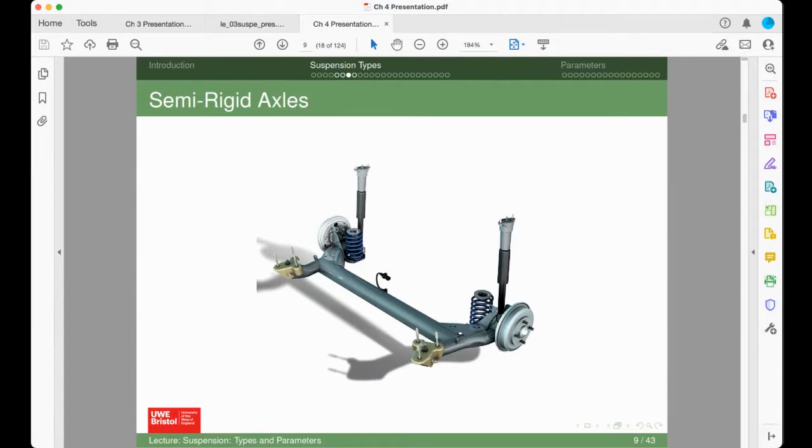You can see these points here, which is where the axle is fixed, with those three studs, and then they're both trailing arms, but they're connected together with this sort of beam between the two. And clearly, you haven't got independent suspension here, because what happens on one side will be transmitted across the axle to the other side. But because of the shape of this and the size and the fact it's hollow, there'll be some compliance between the two, so you get a little bit of independence. But like I said, this is a very simple setup for rear suspension that's been used many times.